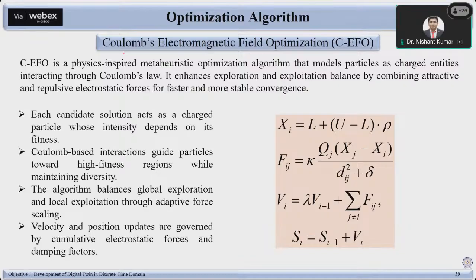at a 100 kilohertz speed, right? Suppose you have decided that you will trigger your system, or you will finish your mathematics within a second or within 5 seconds, suppose you are saying. So what does it mean? It means that data is coming at a 100 kilohertz speed, and you have taken 5 seconds. It means 500,000 data, indirectly 5 lakh data you are going to get through one sensor.